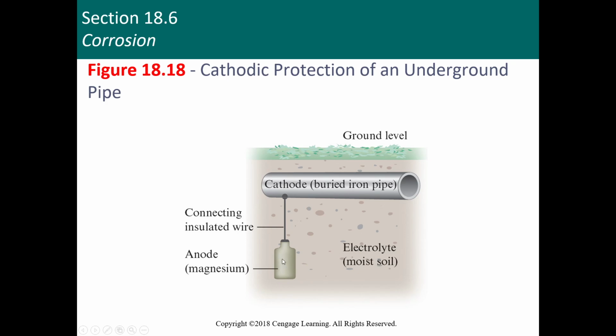Typically, you use a little piece of magnesium. And so this will slowly corrode. It'll act as your anode. You'll lose the magnesium. You won't lose any of the iron. That will stay complete as a pipe or tank or whatever. Your electrolyte is actually your moist soil, if you're curious. This is one of the reasons you always have to do some sort of cathodic protection, is your electrolyte is in contact all over your cathode right here, which is that buried object, because soil typically picks up some degree of moisture, which is called your groundwater.